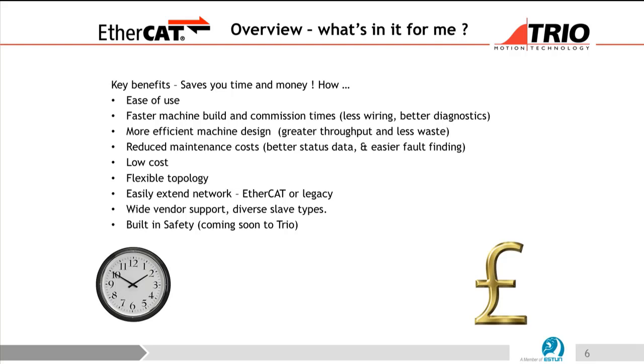So there are so many slave devices in the market. There are EtherCAT stepper drives, EtherCAT servo drives, EtherCAT IO devices, EtherCAT thermocouplers, and so on. Encoders as well. So no license on slaves, but license for masters. Which I would say is very convenient, because you're only going to have one master, but many slaves. Yes, so that's why it's getting more and more popular.